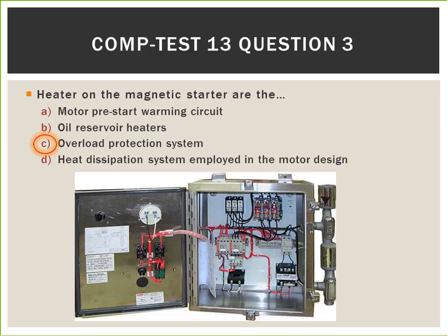Answer C is the best answer here. Heaters on a magnetic starter provide overload protection. Heaters on a magnetic starter do not provide a motor pre-start warming circuit, do not function as oil reservoir heaters, and do not provide heat dissipation employed in the motor design, and therefore answers A, B, and D are all incorrect.